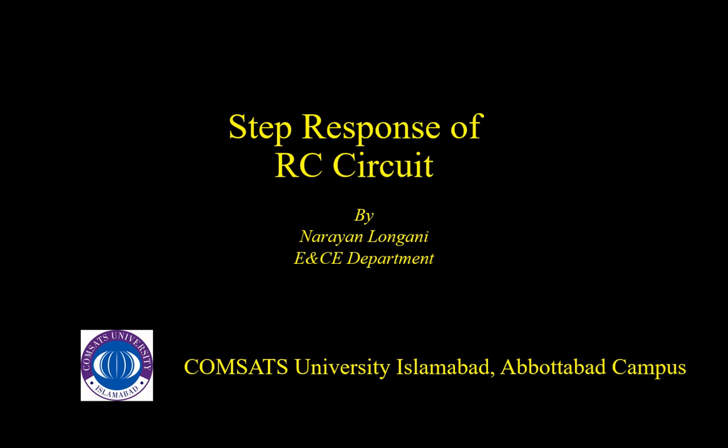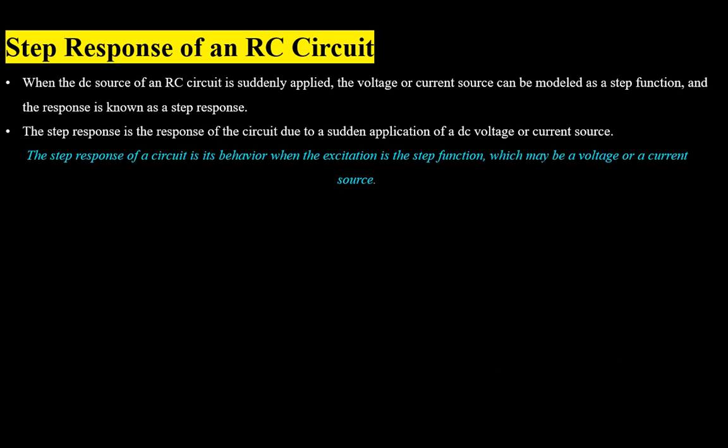Now in the analysis of first order circuits, we will study the step response of an RC circuit. As discussed earlier, we know that first order circuits can be excited by two methods. The first method is to use the initial condition of the storage element, and it is assumed that the storage element was initially charged, and these circuits are known as source-free circuits. The second method is to excite the first order circuit with the help of independent sources.